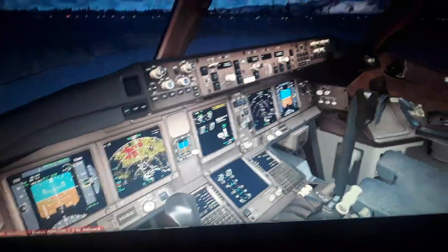I'm gonna show you the autopilot engage and disengage switch, the auto throttle left and auto throttle right engage and disengage switch, and the flight director engage and disengage switch. We have the airspeed select knob. We can select an airspeed in knots or Mach speed, and select the modes that command the engine's thrust rating or rotation speed of the fan. So this is done automatically. I'm gonna show you in a couple of minutes.